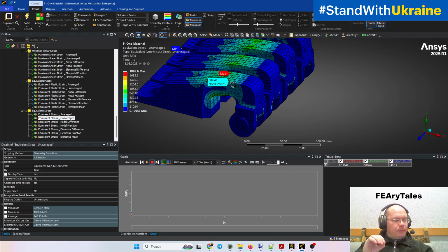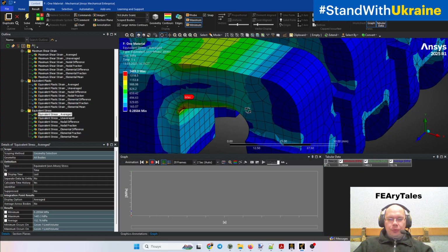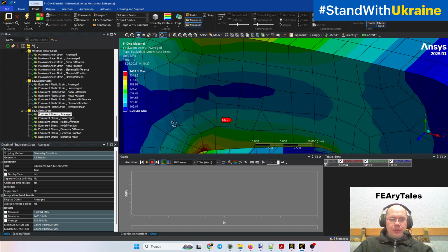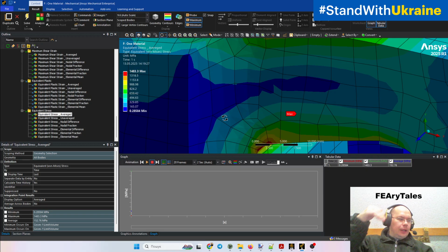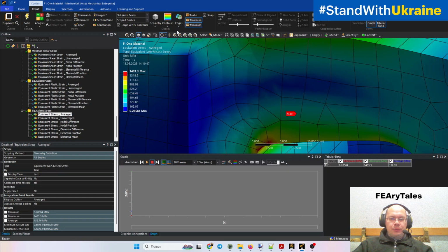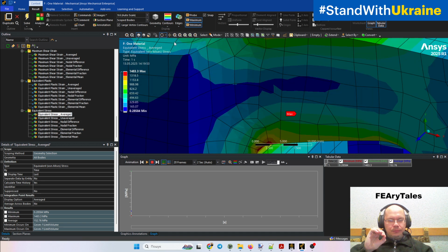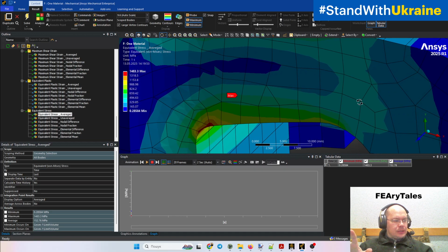Additionally, if we take a more detailed and closer look at those meshes and those results, we will see the difference. When we take a look at the averaged result, we can see that we have a very smooth picture here. Yep, we have the gradient between those two regions, between those colors, but it's the option about smooth contour and not smooth. We use not smooth contour bands for better understanding of the difference. And yep, sometimes it has some peaks, like here, some waves, but in general it's continuous. We have the one line which has some waves, some peaks, but it's the one line.